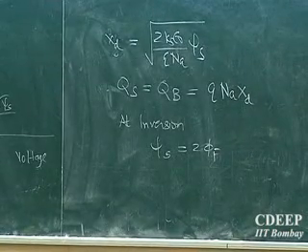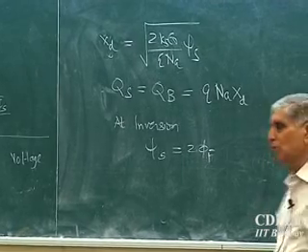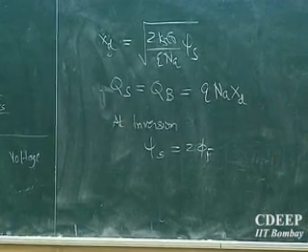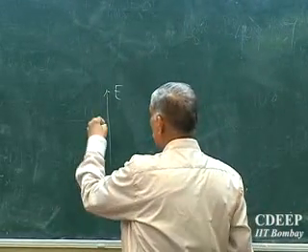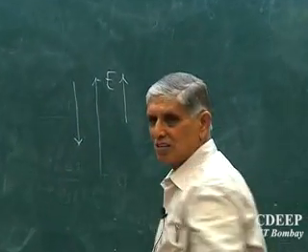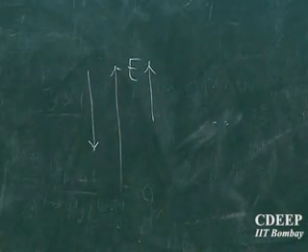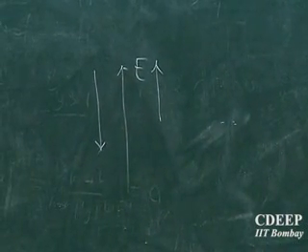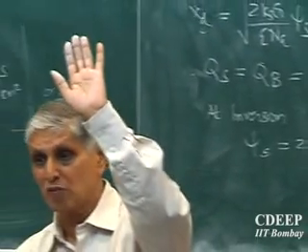Okay, EI minus EF is the Fermi energy, and please remember, in all band diagrams, this is energy. So which side is increasing energy? This is increasing energy. So what is the potential direction? Downwards, minus QE is downwards, is that correct? So potential is downwards and energy is increasing upward. This fact has to be understood.